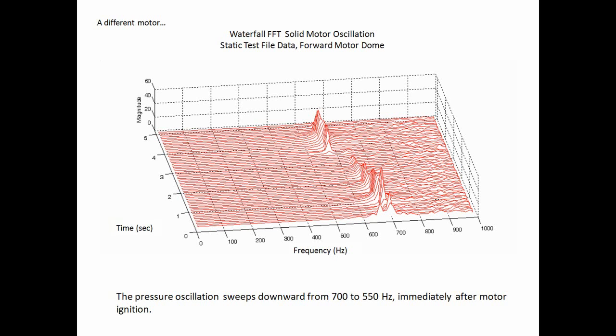So for the static fire test, this vehicle was mounted essentially close to the ground, just maybe a foot or two above the ground. And it was horizontal. The longitudinal axis of the motor was horizontal with respect to the ground. And it was enclosed in a frame made of heavy-duty beams, so that the motor could be lit off, but it would just remain stationary, as mounted to what's called a test stand. It's mounted to the heavy-duty test stand.